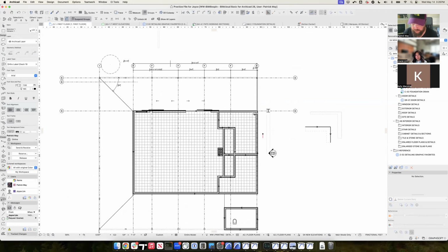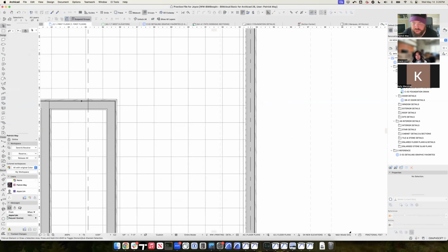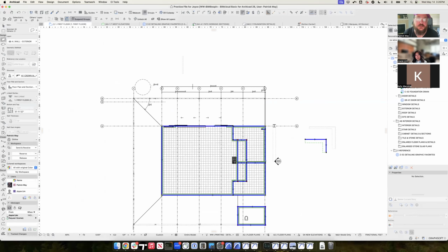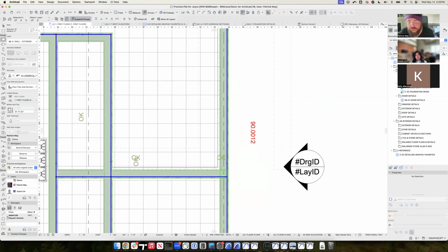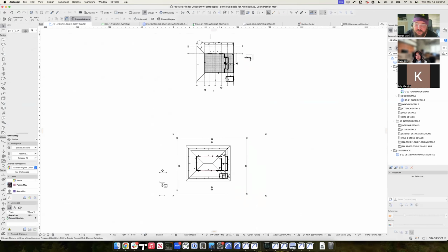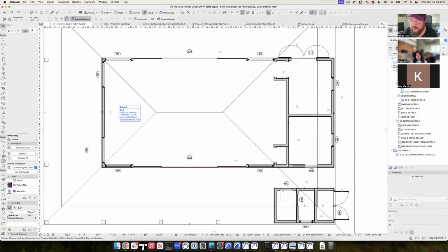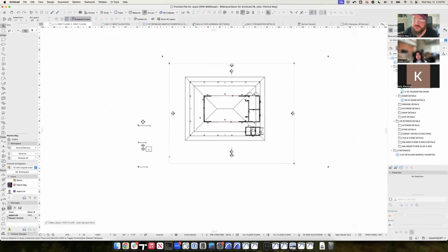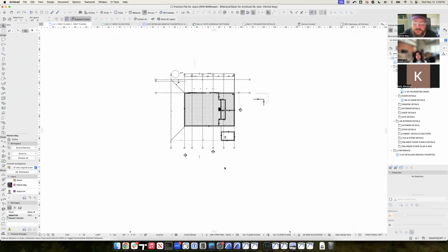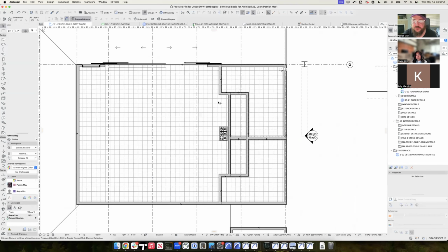So there's a way that you can, for example, grab all of your walls and go to Document, label selected elements, and you can attach that ortho check label to all of the walls in the project just to verify that everything is orthogonal. So down here under this model portion that you were working on, it looks like everything's orthogonal. It's perfect. And then it's just a temporary thing, like a red flag for checking whether things are out of ortho or not.